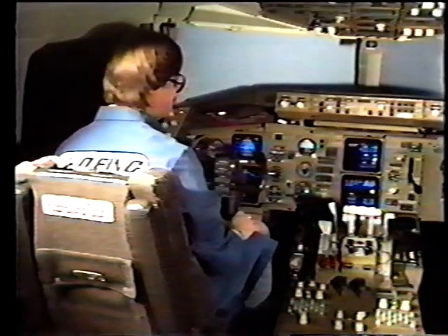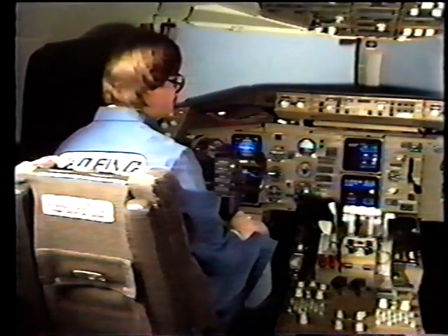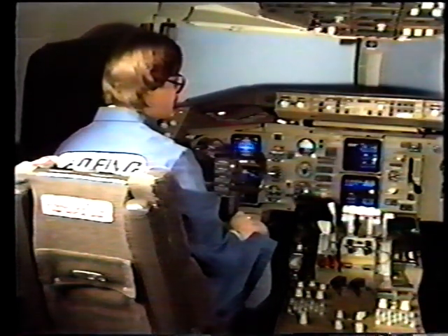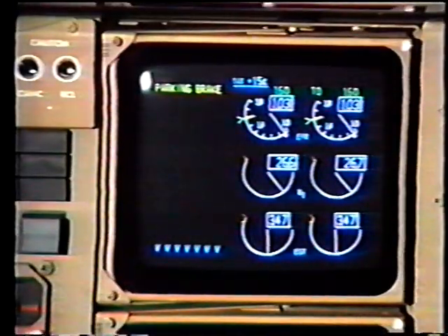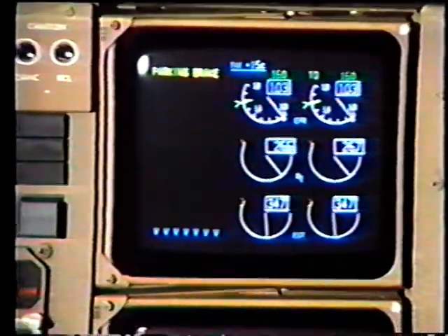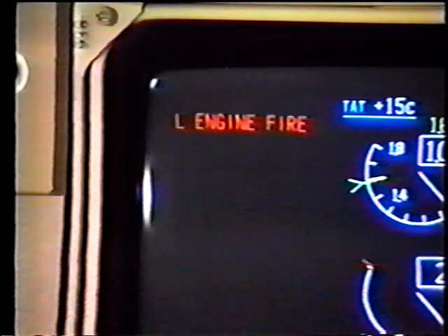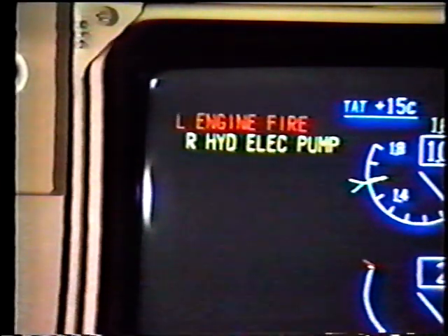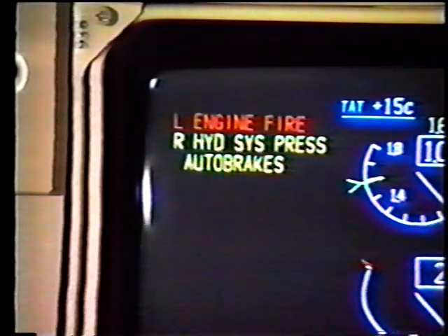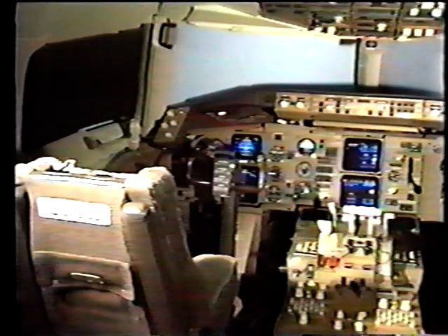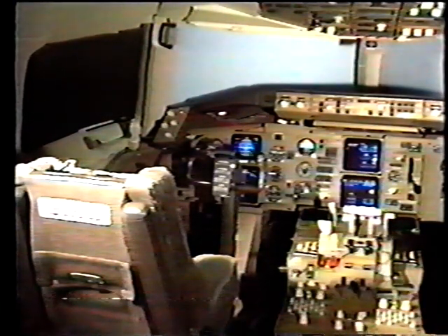This concludes the module on the ICAS system for the 757, powered by the Rolls-Royce engine. It has covered the upper CRT engine display, the lower CRT engine display, failure displays, warnings, cautions, advisory messages, and the location of major components within the ICAS system.